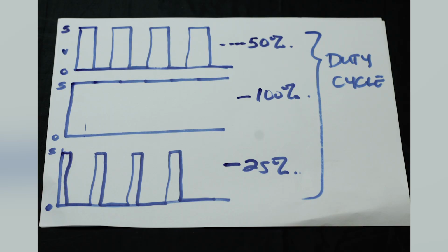For the people who want to explore the technicalities, this entire process is referred to as the duty cycle. We won't jump into those details, but this is what you need to understand why the LED looks like it's on, and when I change that value, you're going to see why it looks like it's off. We got deep there, but I hope you're still with me.